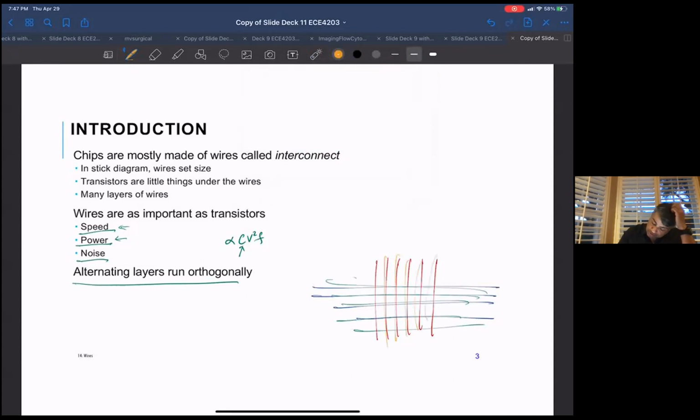If you don't do stuff like this, you're almost surely, sooner rather than later, going to get into places where you're just not going to be able to route through. If you have metal two running both vertically and horizontally, all of a sudden you get to a dead end, and then you're going to have lots of problems.